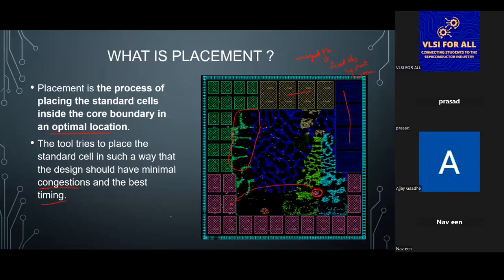So what I can do in magnet placement is give this macro name as an object, and I can give the list of cells. When I do placement again, this cell will sit here. That's how I can improve the timing.